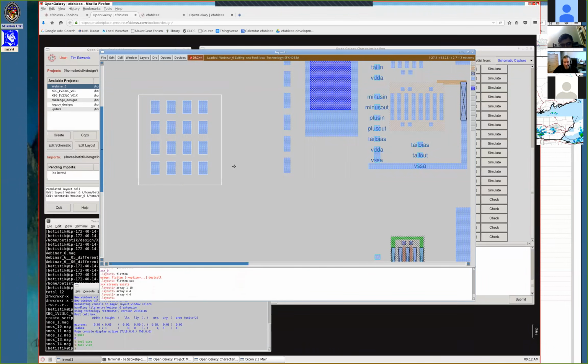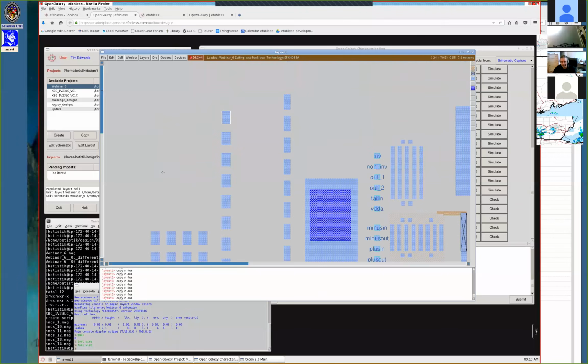There's an additional one too that you can use, which is to select the paint and then say copy north 2 microns, or copy north 4 microns, and you can use the up arrow on the keypad to bring back the last command, so you can just keep doing that. Obviously, the array is a more efficient way to do it all at one go.